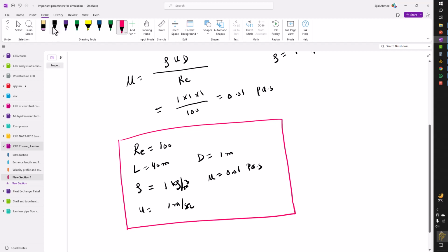Okay, one more thing that I want to discuss here. Sometimes you may see different units in the fluid. The main unit we use for viscosity is Pascal second. So now let's dig more into the Pascal second. This is like Newton per meter square into second. And now you know that the Newton, the force, is equal to m into a. So we know that the units would be kilogram into meter per second square.